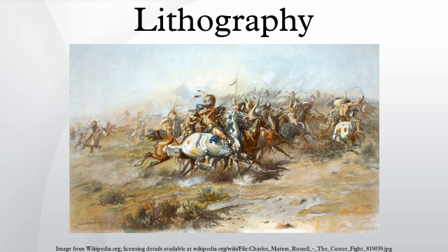The paper passes between the blanket cylinder and a counter-pressure or impression cylinder and the image is transferred to the paper. Because the image is first transferred, or offset, to the rubber blanket cylinder, this reproduction method is known as offset lithography or offset printing. Many innovations and technical refinements have been made in printing processes and presses over the years, including the development of presses with multiple units that can print multicolor images in one pass on both sides of the sheet, and presses that accommodate continuous rolls of paper, known as web presses.